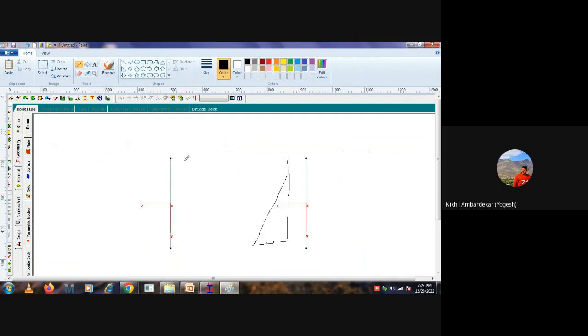And for this wall, your load will be like this. Correct. So for this wall, what will you do? Positive load. Correct. For this, you have to go positive. So now what happens? You have to apply this same value of load 2 times. For this wall, you have to go with minus, and for this wall, with the plus. So if your global axis for this is like this, then in a single command you can apply this load to all walls.